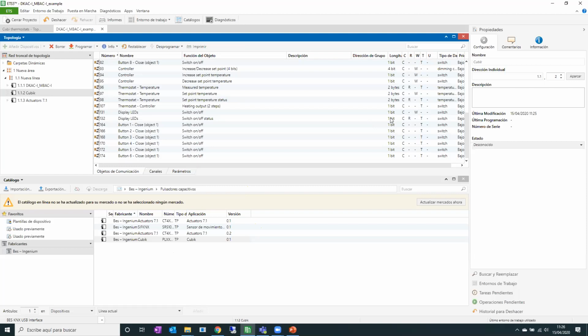The first source, the underfloor heating, is easy because we'll use the TL thermostat in PI, proportional integral mode, of the room temperature controller, and there will be an output from 0 to 100%. And we'll use the normal heating output to be connected with the valve actuators.